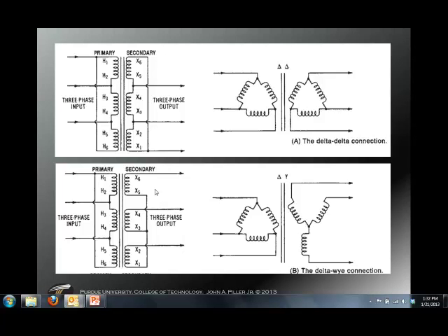The Y would set up with A leg, B leg, C leg, and then we bring in the low side of each of the 3 coils, tie them all together. That would be our neutral point, so you can tie on a neutral right there. So that would be the way we would arrange single-phase transformers to do a delta-delta or a delta-Y.